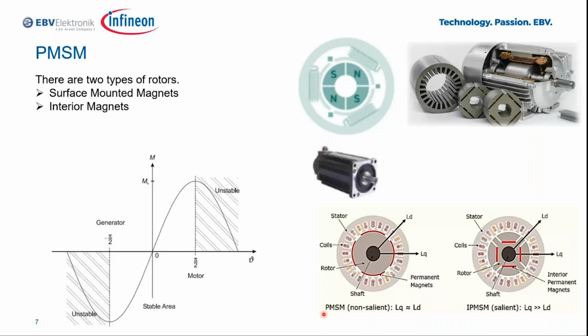The D-axis refers to the direct axis. That means the main flux path axis of a synchronous machine, while the Q-axis refers to the quadrature axis. The load angle describes the angle between the rotor and the stator fields.